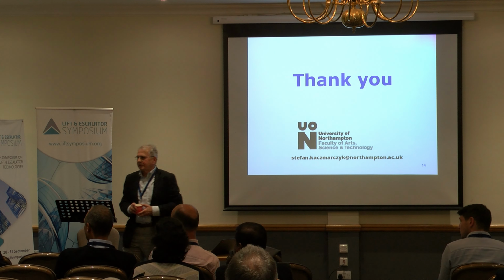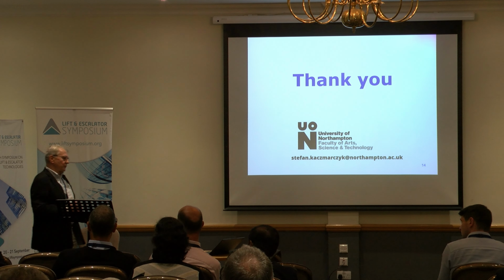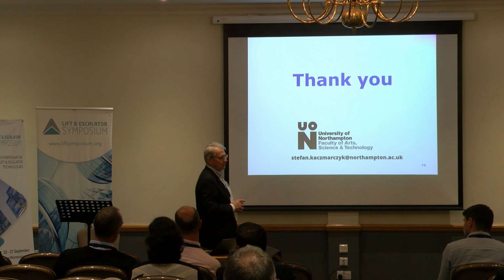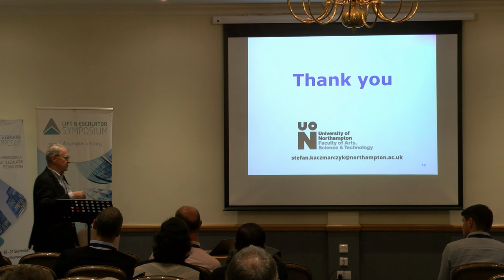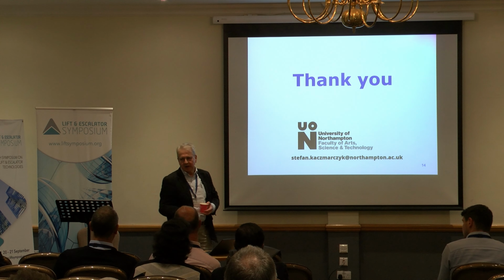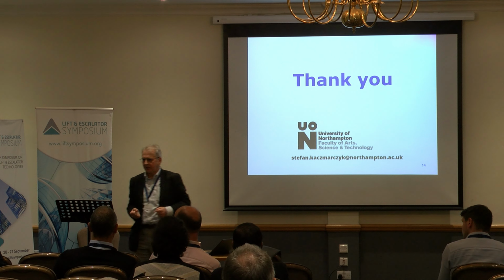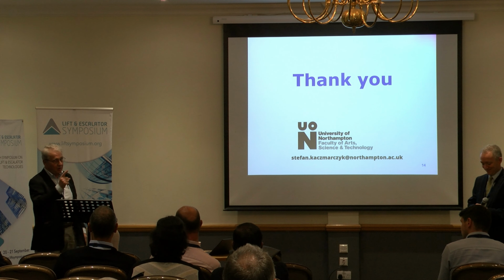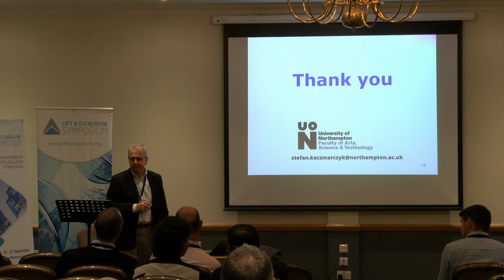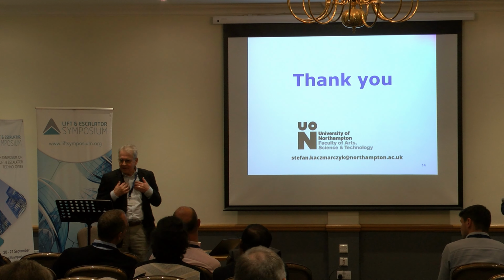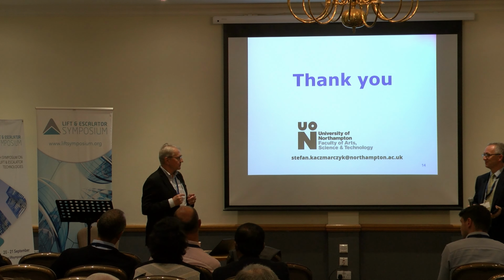So just a comment. I mean, the slope angle seemed to me larger than I would have expected. It depends on the type of the rope. If you take an 8mm rope, it will be very negligible. But if you take 11mm rope, and we know that in high-rise application you use ropes are over 20mm, and I think you handle 20mm ropes. You take the 100mm rope and try to bend it. That's a bending stiffness. But it goes over sheave, you will see that there is transition period. Okay? So I think it lets us understand better mechanics of rope-sheave interaction. Thank you.